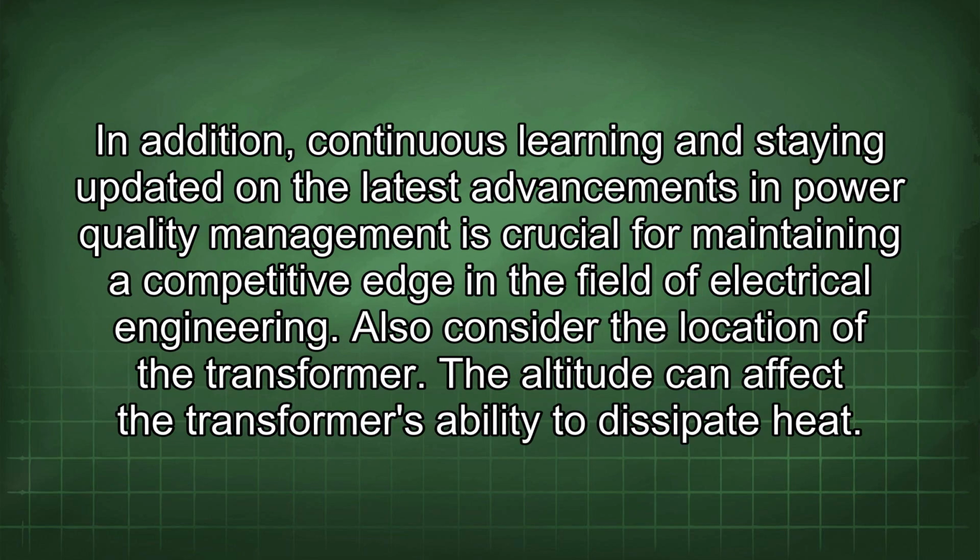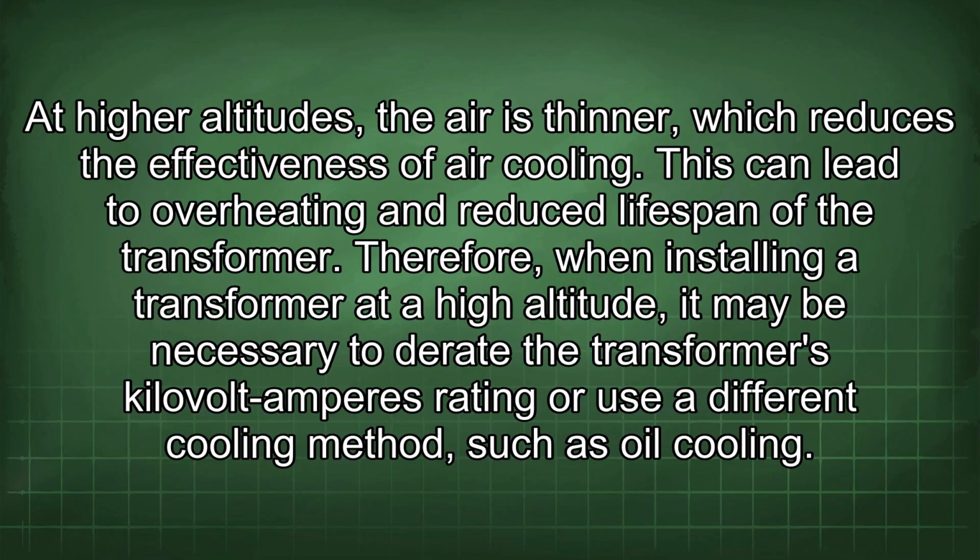In addition, continuous learning and staying updated on the latest advancements in power quality management is crucial for maintaining a competitive edge in the field of electrical engineering. Also consider the location of the transformer. The altitude can affect the transformer's ability to dissipate heat. At higher altitudes, the air is thinner, which reduces the effectiveness of air cooling. This can lead to overheating and reduced lifespan of the transformer.